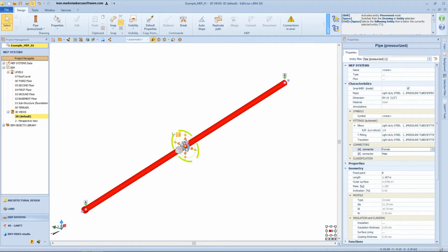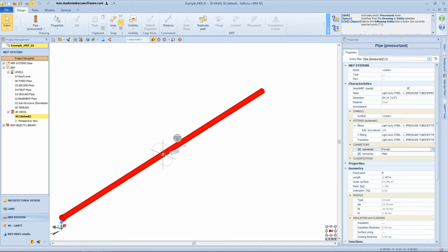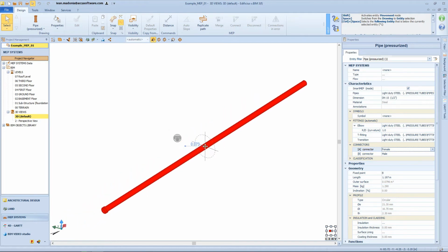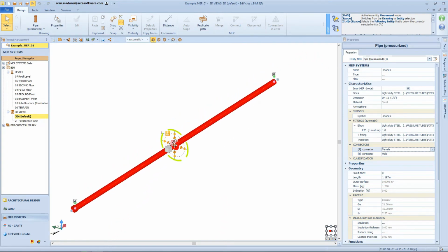By selecting the orange circle or the blue ring that surrounds it, the pipe will still be hooked to the mouse to be moved at a chosen distance with respect to the initial positioning point. In particular, starting from the selection of the ring, this remains visible during the movement, indicating the plane perpendicular to the axis of the pipe on which the movement itself is constrained.